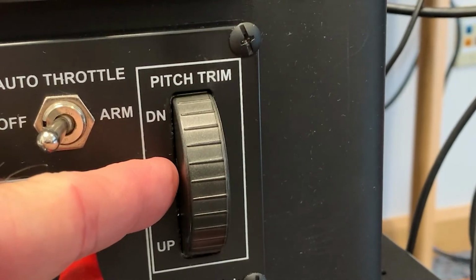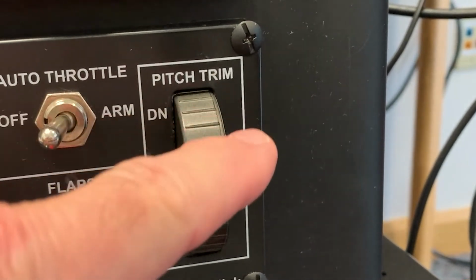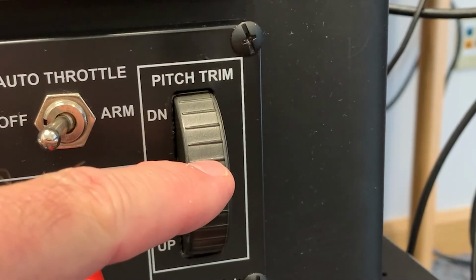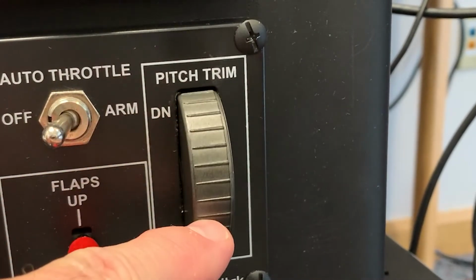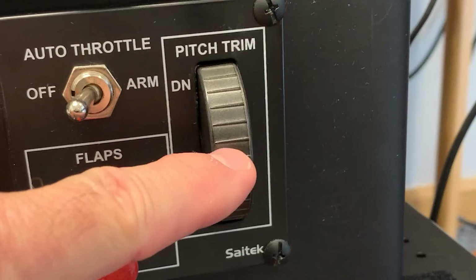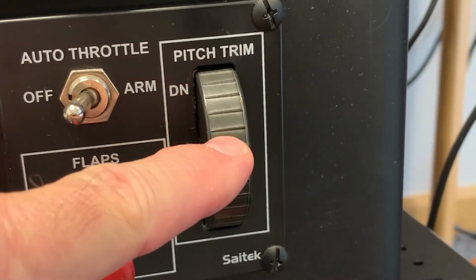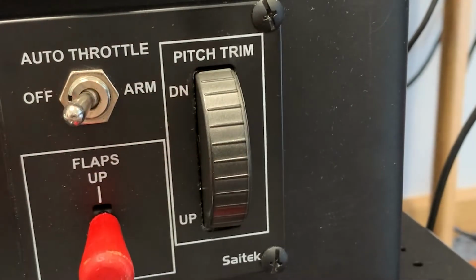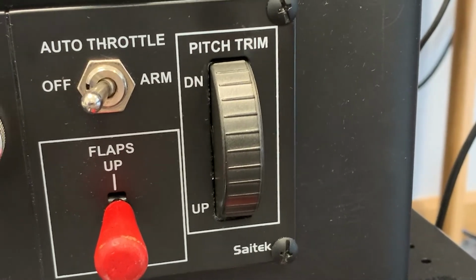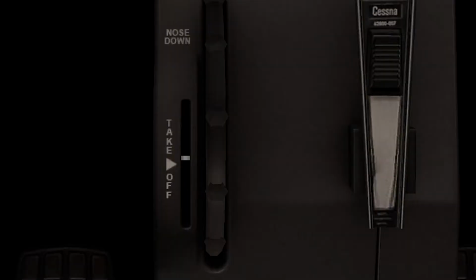Controlling the trim tab is done by rolling the trim wheel forward for nose down trim or backward for nose up trim. I'll explain how this affects your speed in another lesson. For now, just know that if your plane tends to go nose up or nose down without you moving the yoke, your trim is probably not set correctly. For level flight, it should be in this area.